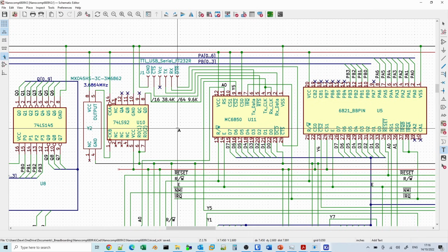What we're going to do now is to start laying out the chips on the board. I'm not going to do a Fritzing layout for this because now that I've got enough space on the breadboard, we shouldn't have too much trouble laying this out and hooking up. And again, what I've done here is I have made the chip layouts in their physical pin arrangement. So you can see here, pin 1 is actually at the top here.